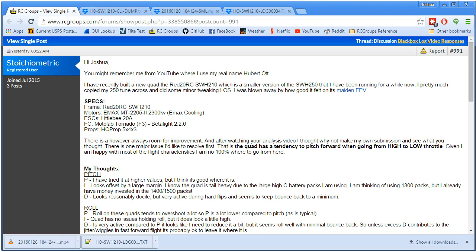In other words, if you were to punch out in a flat hover, you wouldn't get any of this throttle-dependent effect. The copter would just pitch straight up. Well, actually, the CG would affect you just as much when you're in a flat hover, but the aerodynamic effect would be balanced between all four motors.